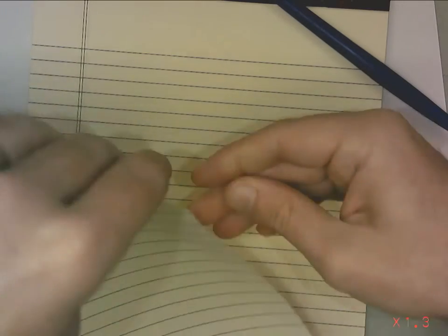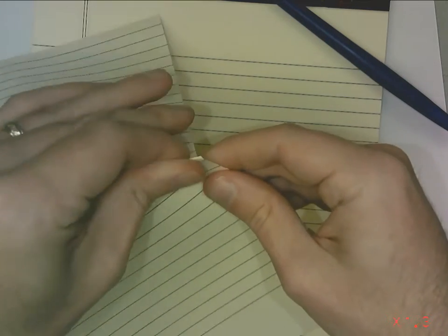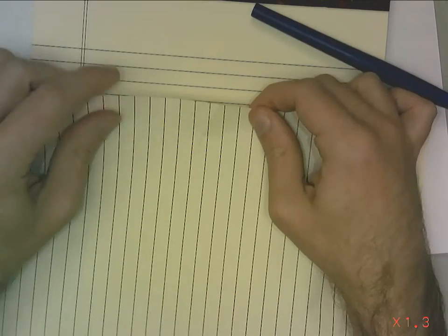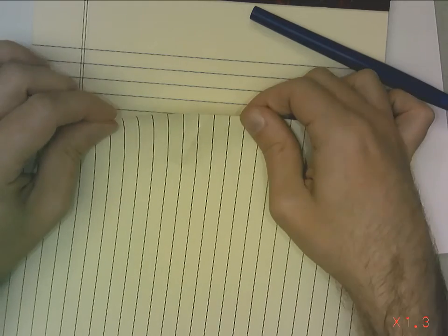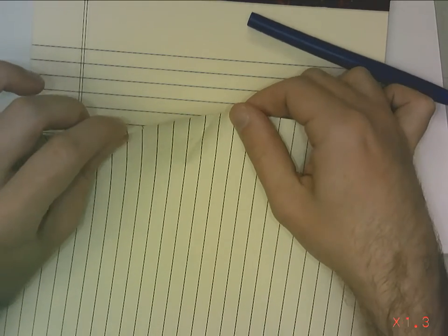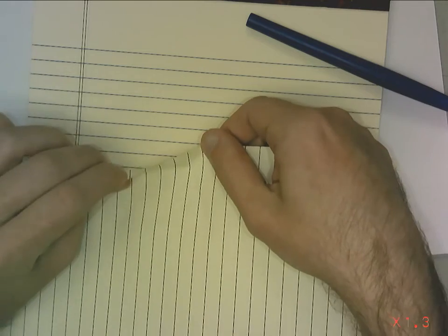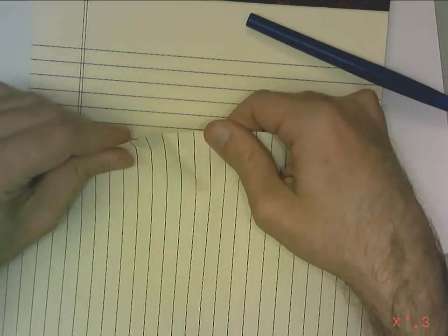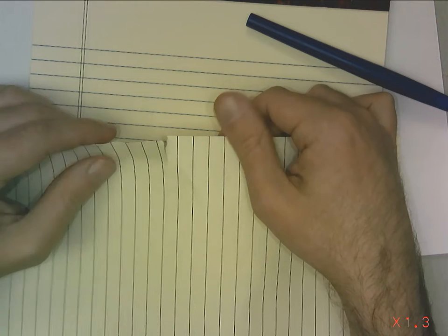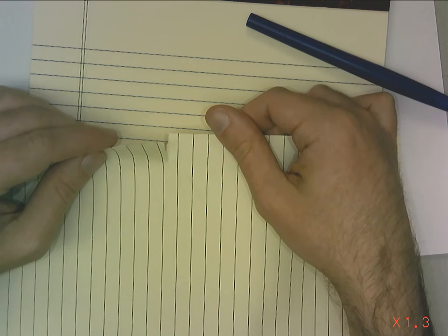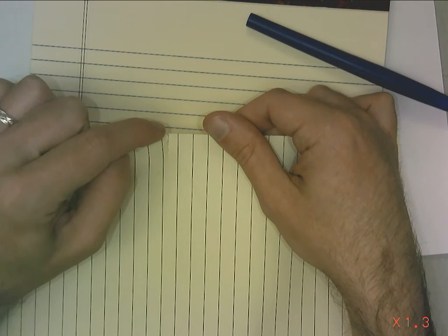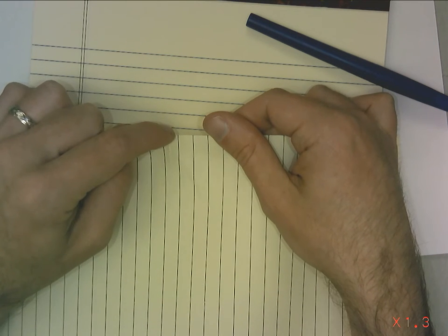If I got a piece of paper and I put a bend in it, fold it over, bend it, regardless of if that's right in the middle and I offset it, where do you think it starts to tear when we start to, this could take a while longer than what I intended it to. There we go. It starts to tear where I already had a bend or a geometric discontinuity.